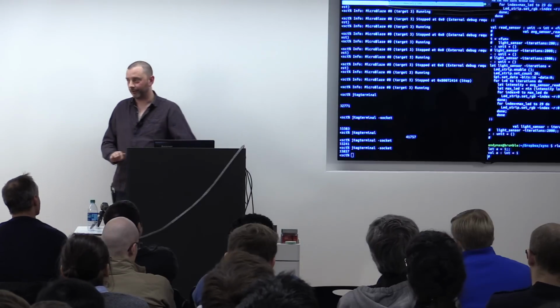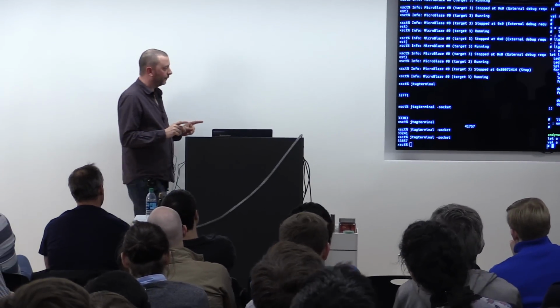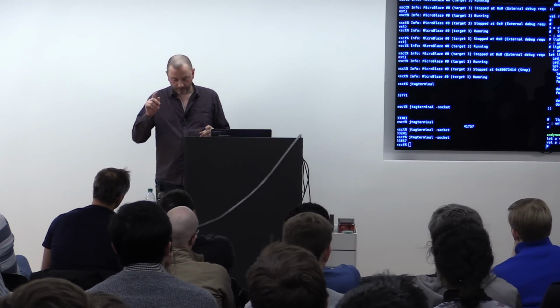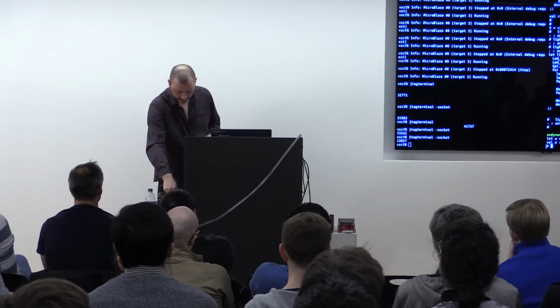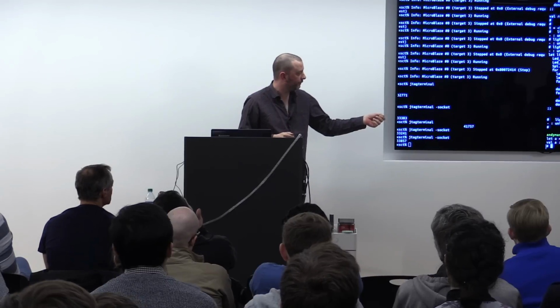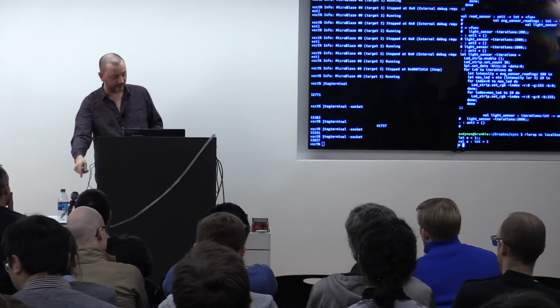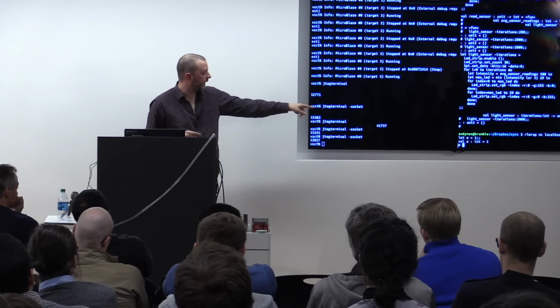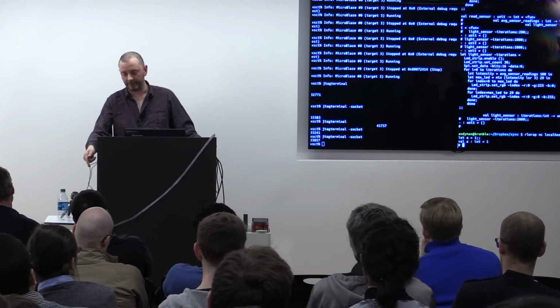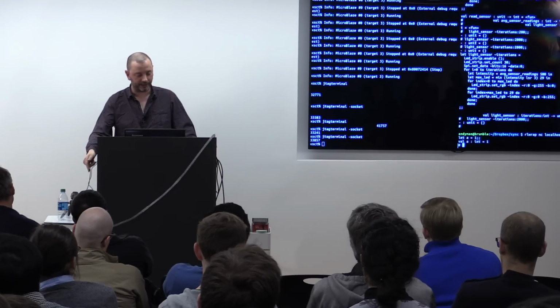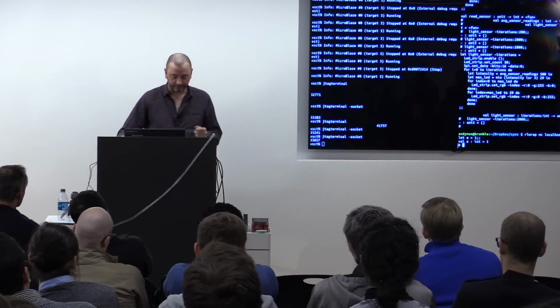Yeah. So, what just happened there? Well, the processor is redirecting its standard in and standard out through this USB cable up to a driver on my laptop, which is then bridging that across onto a TCP socket, which I'm then attaching to with netcat. So I typed stdin, stdout goes down to there. When I typed let a equals 1, that was compiled by the FPGA, or at least by OCaml on the FPGA, and it showed the result.